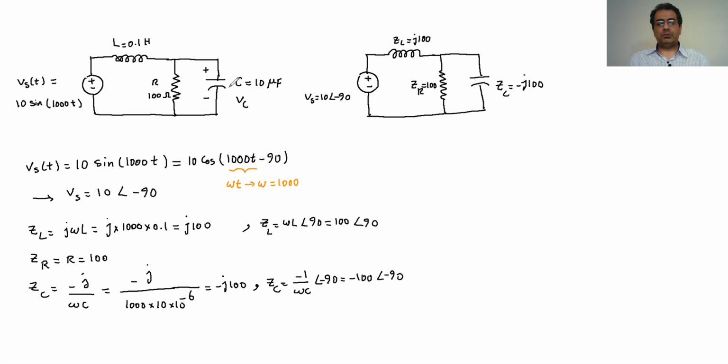Assume they behave as resistances, two resistances in parallel. Whatever voltage I have here, the same voltage I have here because they are in parallel. So I can find the equivalent resistance, or in this case, impedance. Whatever voltage I find for that equivalent element is the same for this one or this one, because when elements are in parallel, the voltage in each of them is the same.